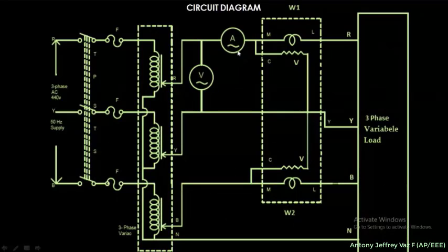This is the circuit diagram. Here, these are the main terminals R, Y, B. This is a three-phase connection available in our laboratory, with a supply voltage of 440 volts. It is highly dangerous. If you carelessly put your hand in this, you will be thrown out. So this is a highly dangerous voltage, 440 volt at 50 hertz supply. The three-phase voltage will be present at this terminal.